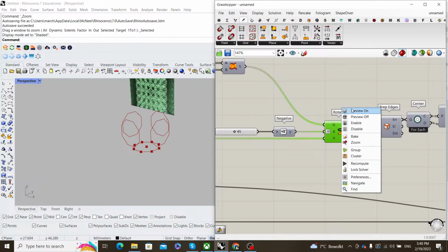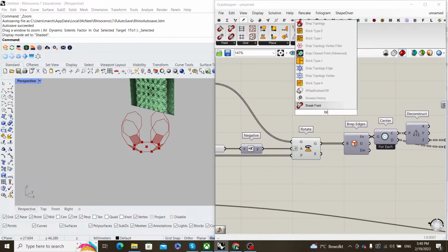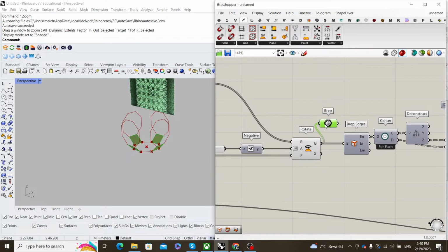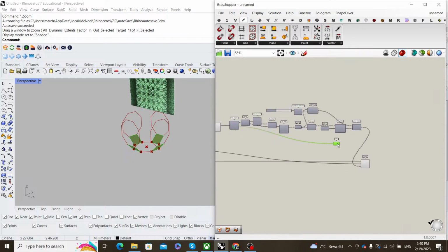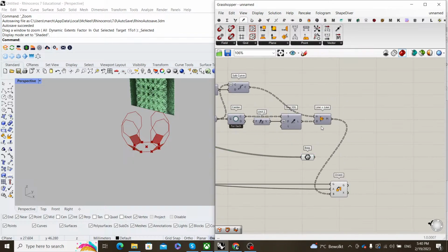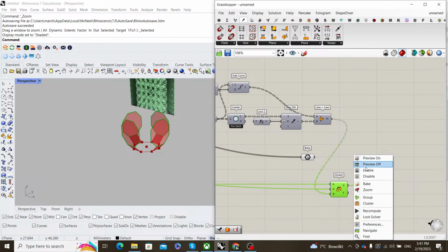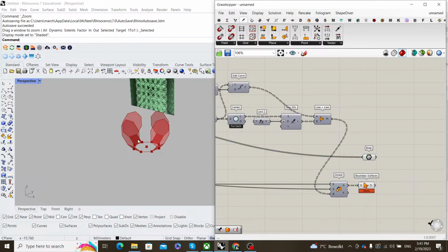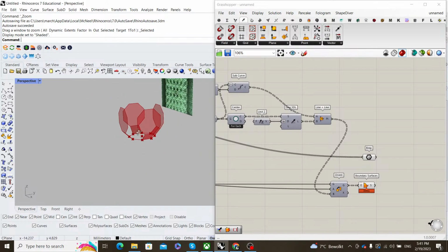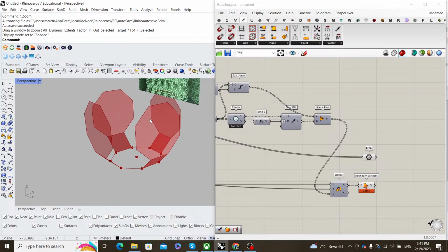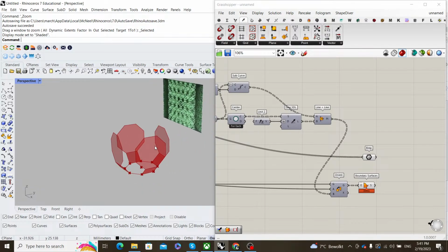Okay, so I keep deleting it, but I should not. I should actually take these B-reps like that. Yeah, so then I will also create boundary surfaces from these octagons because they are closed, they are planar. So why don't we make a really nice closed boundary surface from them?